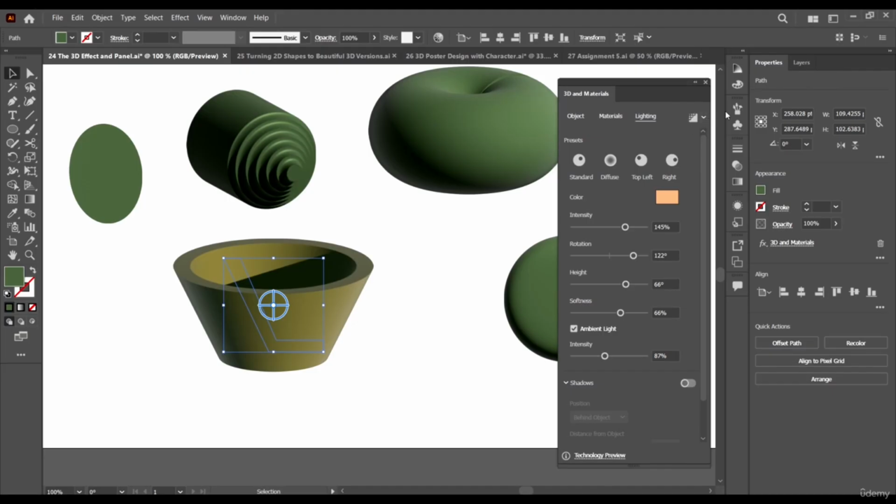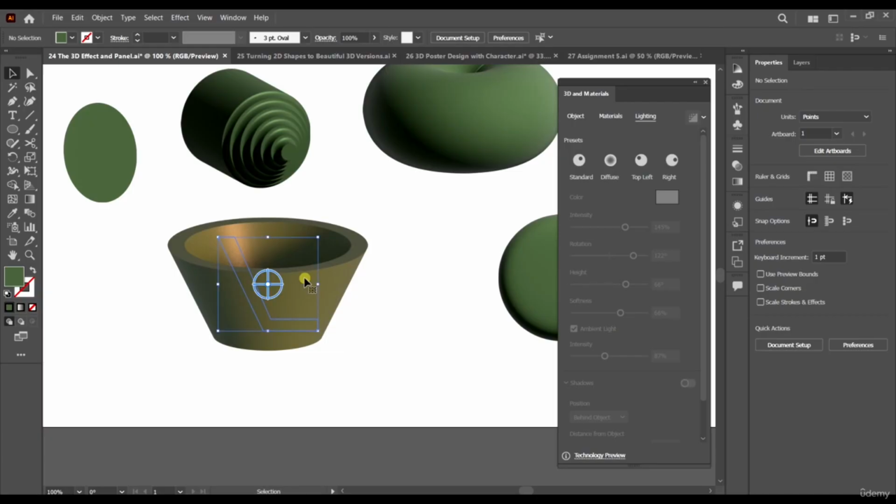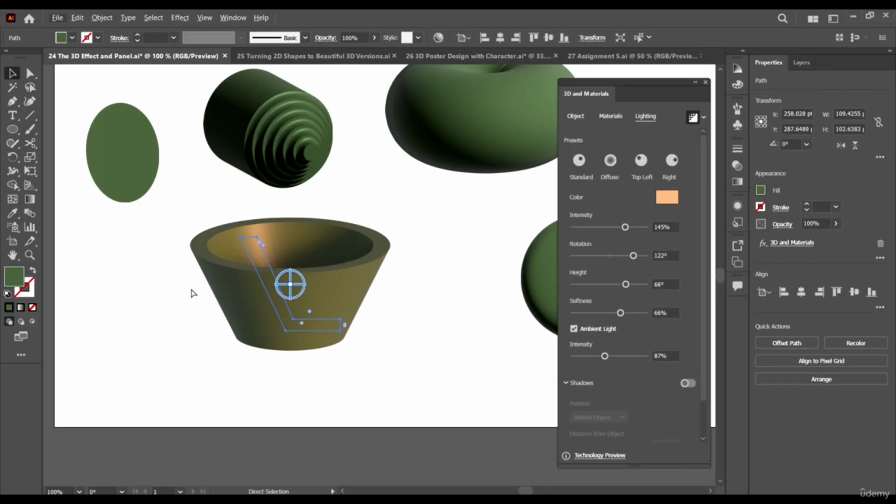And then finally, we have the render settings, right? We can just come here and activate ray tracing, and then choose the render quality. We can make it low, medium, or high. Then activate reduce noise. Let's try medium and then just click render. And it's going to take some time to render. And as you can see, we now have our rendered image.